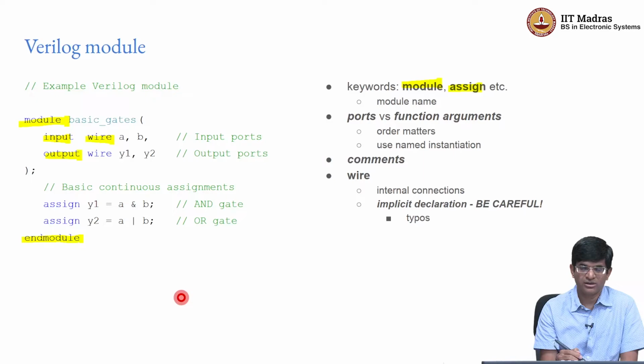In the case of Verilog, it's if anything even worse than both of these conditions. Of course, the first condition, what C does, is probably the right thing to do. You force somebody to declare a variable or a wire name before using it. In Verilog, it implicitly assumes that there is a wire. More importantly, it assumes that it is a 1-bit wire. And the reason why that's dangerous is because very often by having something implicitly declared as a 1-bit wire, the width of ports can themselves get changed without your even realizing that something like this has happened.